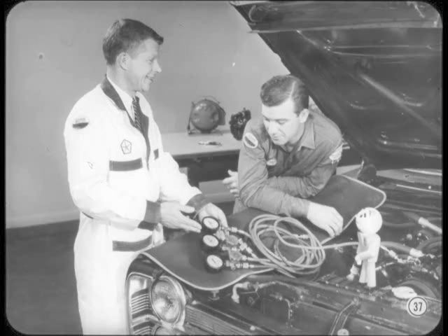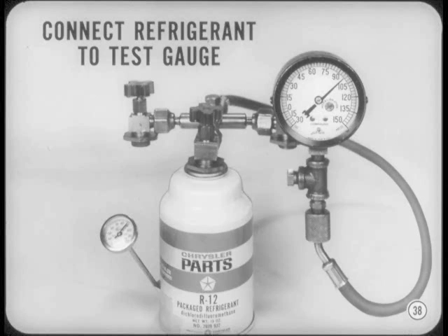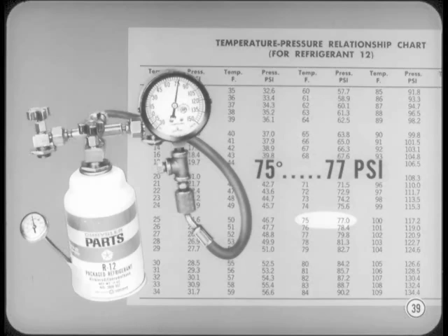You can test the gauges yourself. All you need is a nearly full can of refrigerant and an accurate thermometer. Tape the thermometer to the can so its thermal sensing element is below the liquid level. Then connect the refrigerant can to the hose of the gauge to be tested. Put the whole rig somewhere overnight where the temperature is stable. In the morning, compare the thermometer and gauge readings against the temperature pressure chart in your service manual to check the accuracy of the gauge.